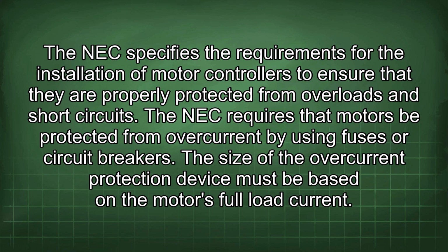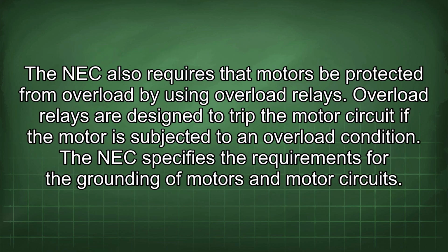The size of the overcurrent protection device must be based on the motor's full load current. The NEC also requires that motors be protected from overload by using overload relays. Overload relays are designed to trip the motor circuit if the motor is subjected to an overload condition.